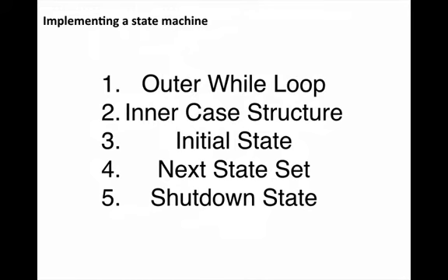The initial state is crucial. A lot of times people will design a state machine and forget to set the initial state. So they boot up and nothing happens, or it goes to a random state, which could be even worse. Often the first state is initialize, which does things like set up the inputs and outputs, do a little bit of housekeeping, figure out what mode we're in, and then go to that state. So the initial state is often initialize. They're similar but different. For example, you could have the initial state be a state called startup.